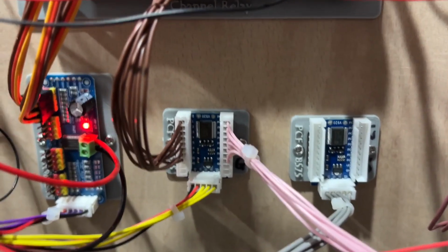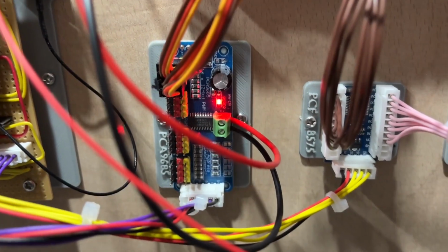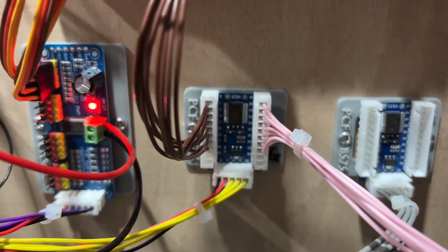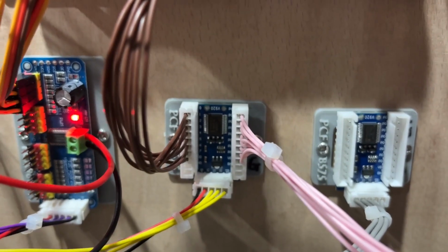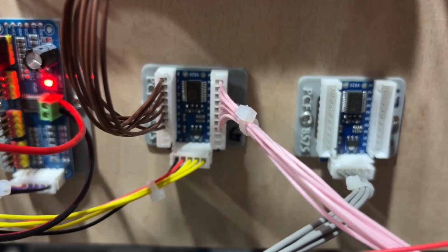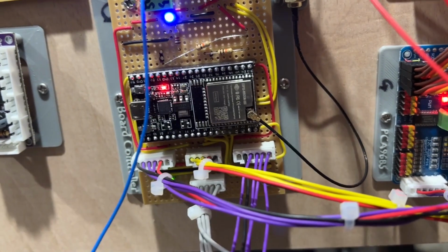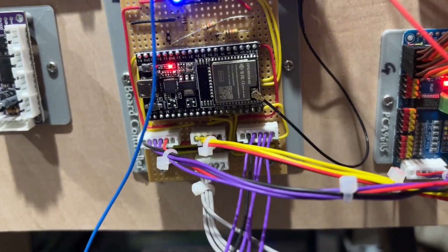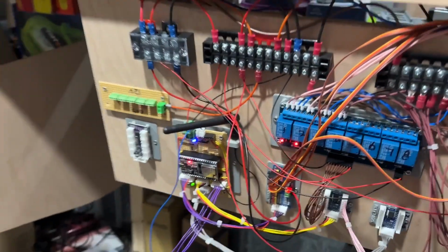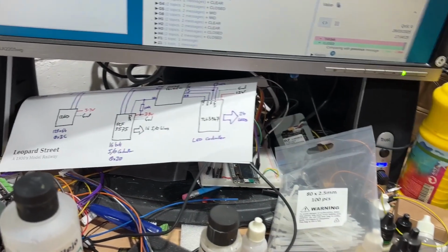Expansion boards. Now these connect to the same control bus actually that controls the servos. These are providing some inputs and some outputs. I'll come on to what the outputs are shortly when we go around a little bit further. So that goes into there. The ESP32 knows, and what it does is very simply, as we did previously, it pushes these out over the MQTT system.